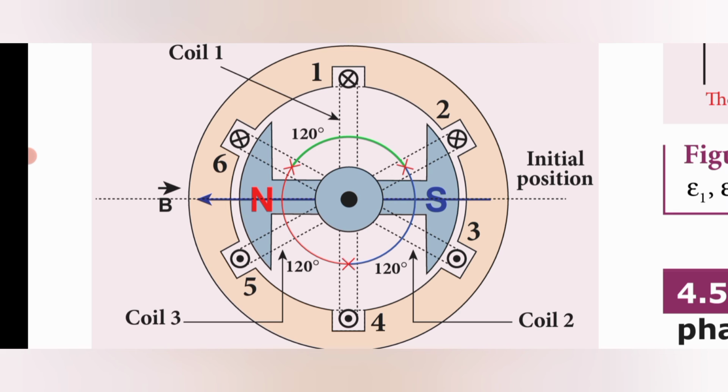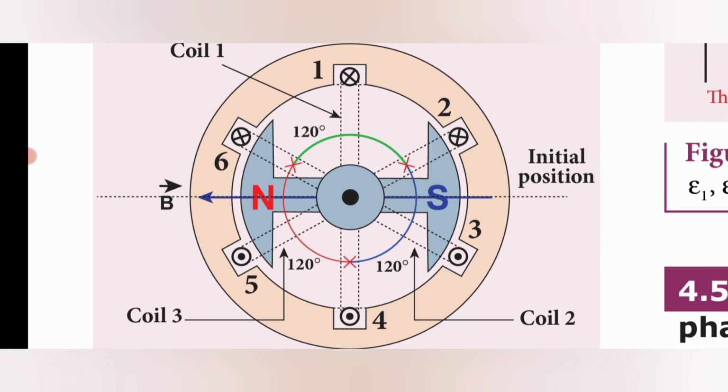That is considered as the stator, and at the center the rotor is used. Because of the rotation of the rotor, the angle changes. The first coil starts from 0, then the second coil starts at a different angle, and the third at another angle. The angle difference between these 3 phases is 120 degrees for each coil. This variation forms EMFs epsilon 1, epsilon 2 and epsilon 3 with a time angle, with a 120-degree phase difference between one another. So this is the 3-phase AC generator.